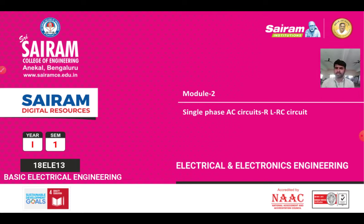If you see an RL circuit, for example, I can say a choke coil. A choke coil for tube lights and CFL lamps is for limiting the fast moving electrons, the fast moving charges, and also for energizing the two terminals of the CFL. For that purpose we want a choke coil, because we want more voltage at the time of starting, but the current should be limited. So single phase circuits: RL circuit and RC circuit. Let's see the circuit diagram.